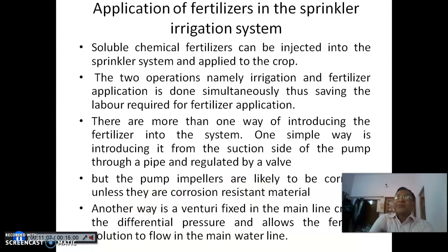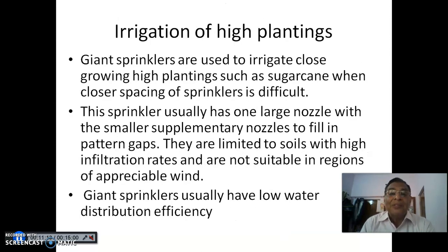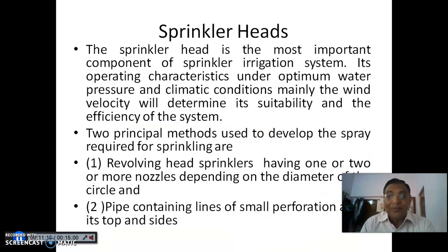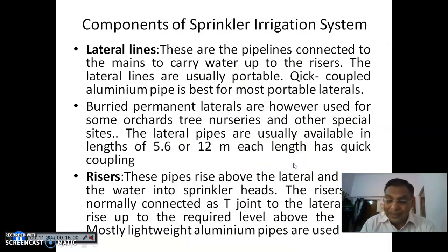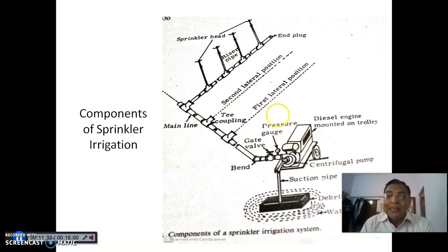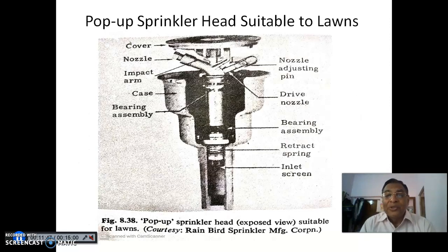So while you are using from the suction side, let us go back to that original figure where we were talking about something. Yeah, when you are introducing from the suction side, then these pump impellers get corroded unless they are corrosion resistant material. So another way of introducing this is from this side here with a valve and then Venturi.